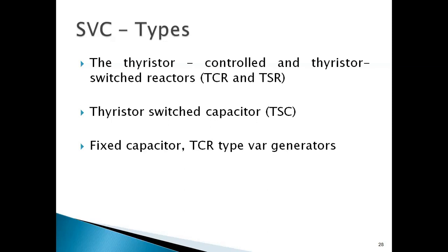In heavy load condition, we face the problem of shortage of reactive power, because of which we are facing low voltage, and we want to increase the voltage or bring it back to the normal voltage. For that we go for TSC. To increase the voltage, we go for a capacitor, as it has the capability of generating reactive power. That is in the case of peak load condition.